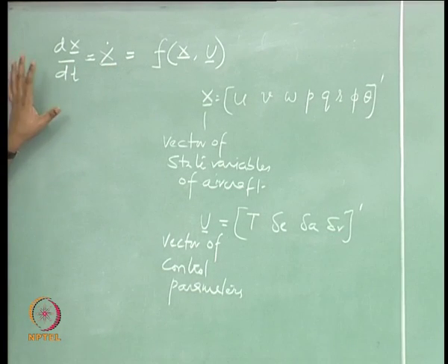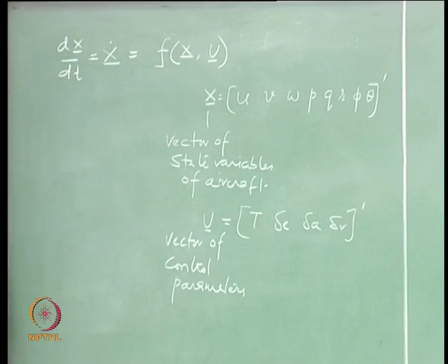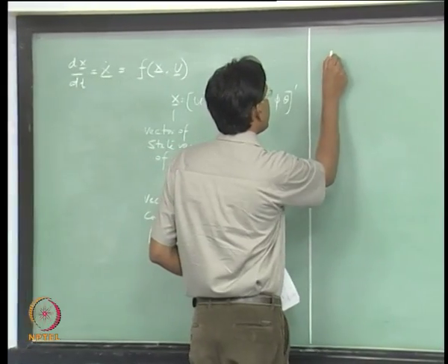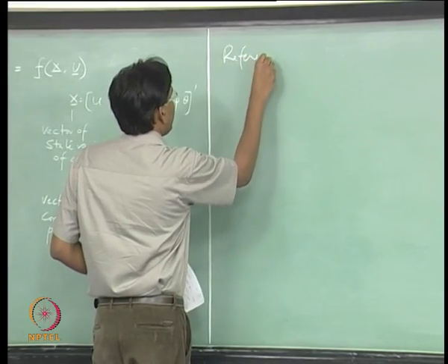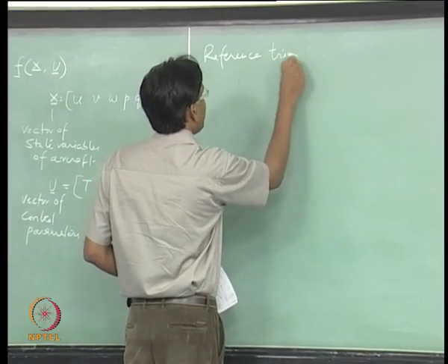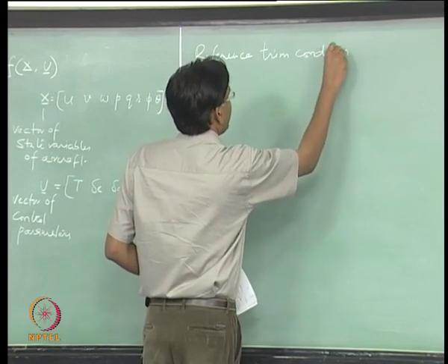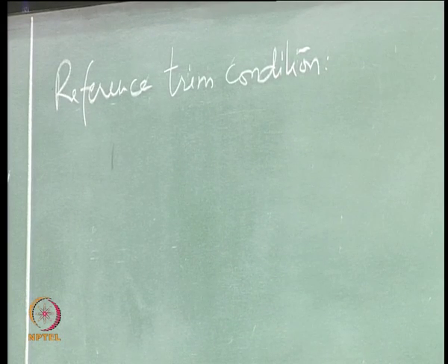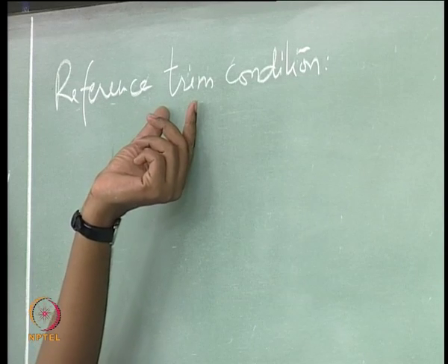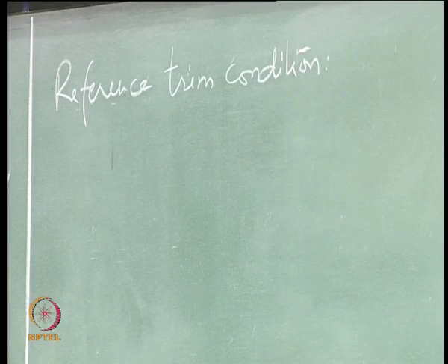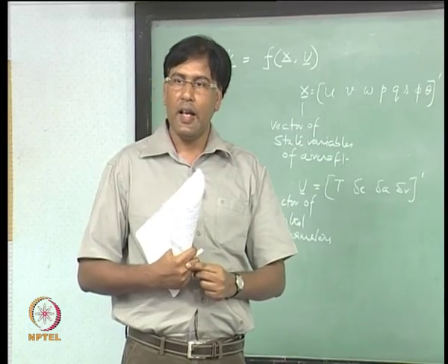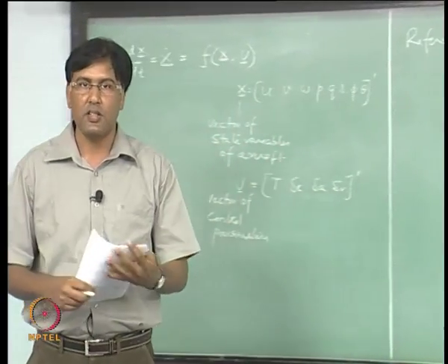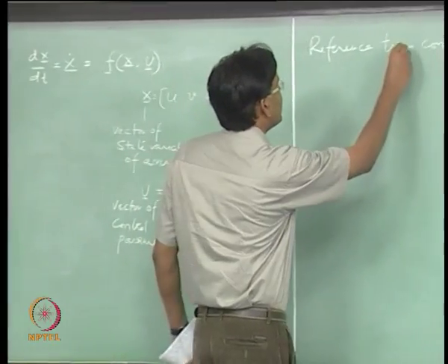Now, what we are trying to do is linearize these equations around an equilibrium flying condition which is a longitudinal trim, right. Trim or equilibrium, sometimes people get confused with this because trim is related to locking your control surfaces, isn't it. So, in a general sense people do not like to use trim for equilibrium condition, but for aircraft it is a valid word.